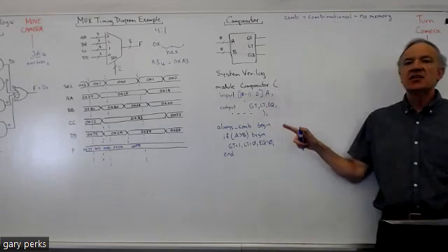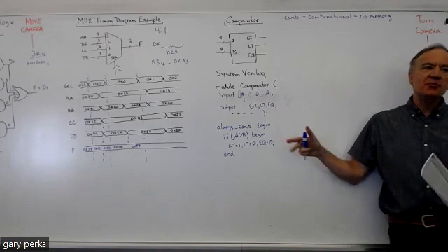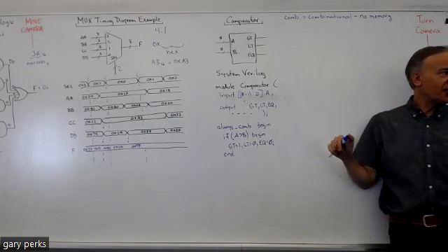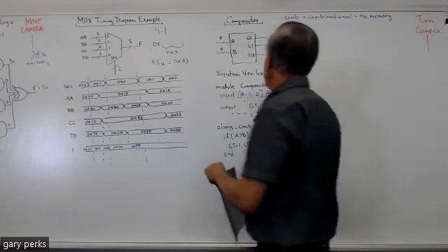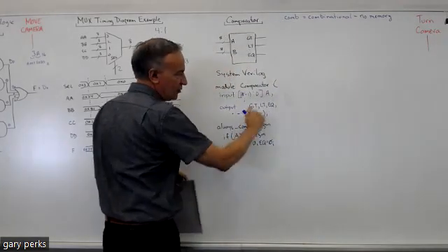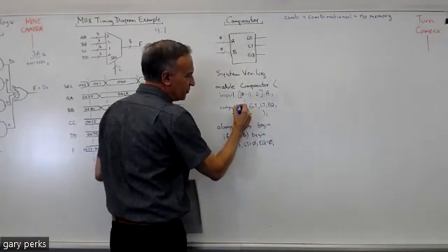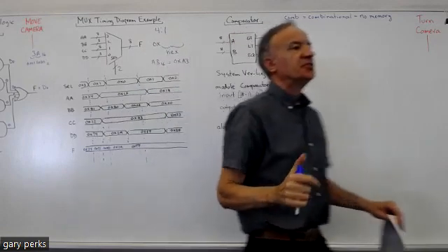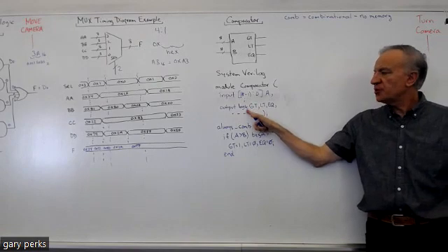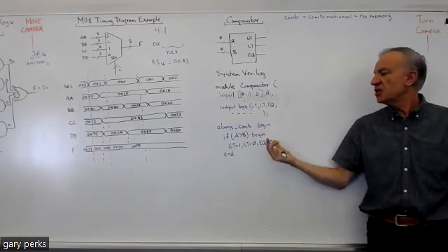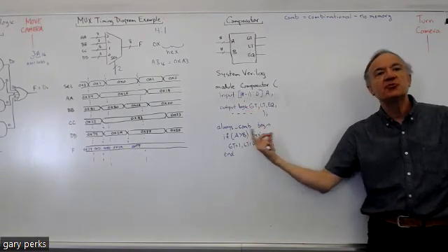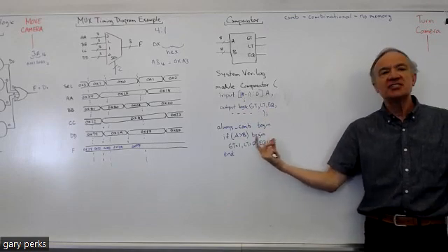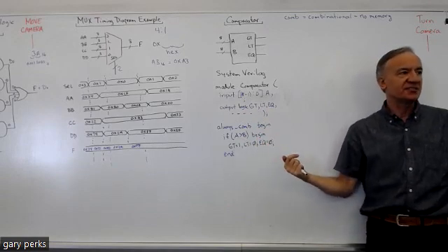Well, when you have an output within an always block like this always_comb, you have to put in between output and the name of the output, you have to put logic. You only need to do this when you have outputs within an always_comb, like an if statement like this.